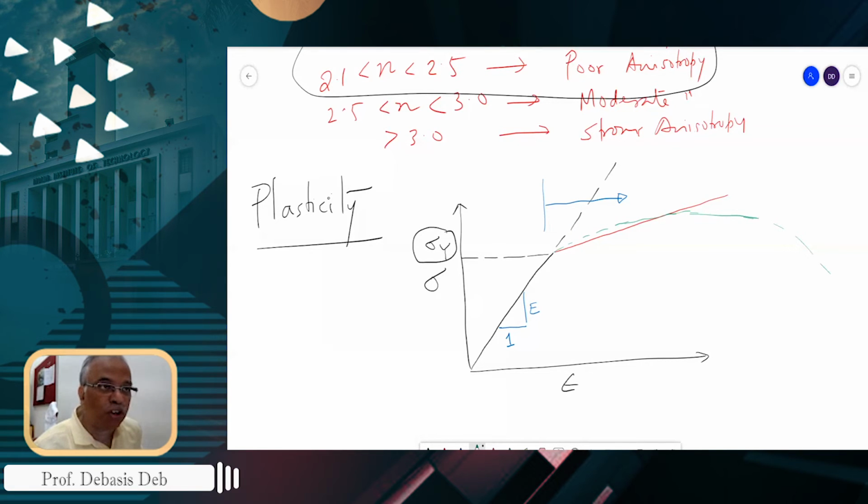So if I want to follow the curve, I cannot take a big step in strain, because I am going to analyze how this curve is changing. So what we normally do is take an increment of strain. That means we take delta epsilon rather than the full epsilon. Epsilon we measure from here, now we will start to measure from here.